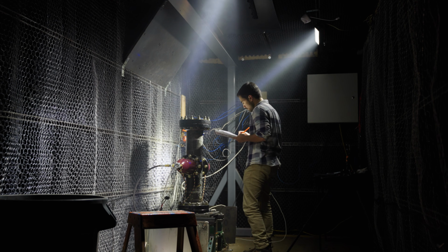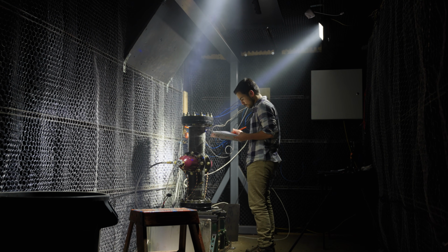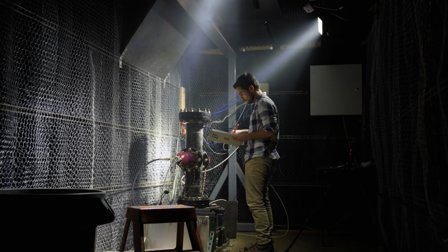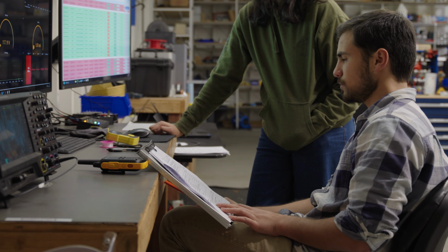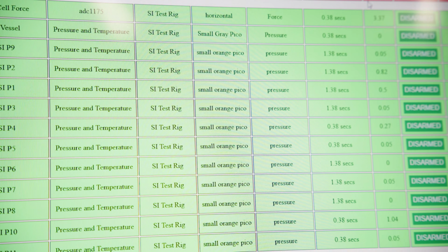So the static test rig and side injection only gets us so far. When things are accelerating, the forces that are seen and the momentum transfers that are observed are very, very different than a static setup. While this static setup shows us kind of a best case scenario, and it shows us a lot about verifying our CFD, verifying our analysis with pressure maps, it doesn't tell us much about how well the accelerator performs with a projectile that is in motion.